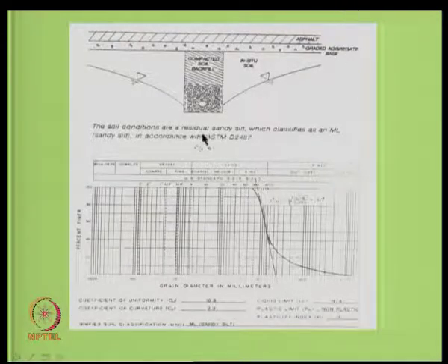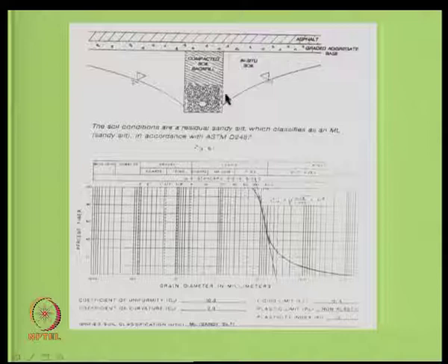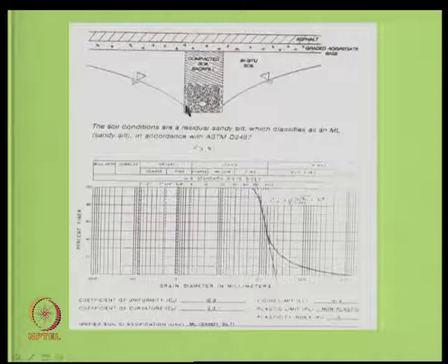Like this is that type actually, what I want to say. Suppose you want to have a sort of a drain system like this, okay, and the objective is to see that water should not be at the top of this, because otherwise it is very difficult to park the vehicles. So, you would like to lower that, and then you came out with a design that it should be about say 1.2 meters below the finished grade, okay. Then what we do is that you also have a gravel here, and you also have a pipe here, and geotextile is placed here.